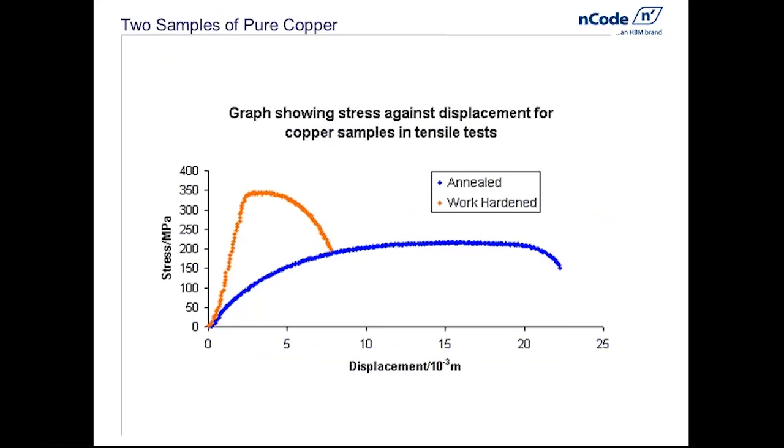Give you an example. We've talked about soft metal and hard metal. Here is one that I've pulled off from, I think it was Dewitt Pond. It is annealed and a work-hardened copper, just to show you the difference. And the difference on the lower left, you can see that the yield strength of that annealed copper is very low indeed. But once you work-harden it a bit, it gets much higher. And the other key point that I would like to show you on this, which of course has direct relevance to the fatigue performance of these materials, is that the ratio between yield strength and UTS is very different for the work-hardened and the annealed material.